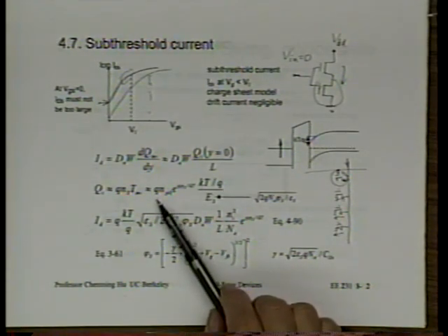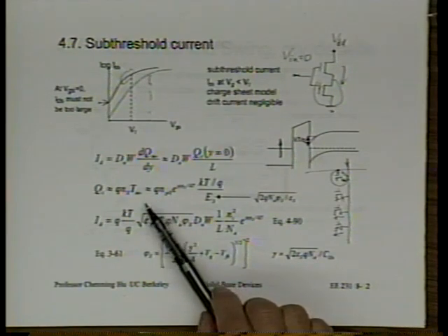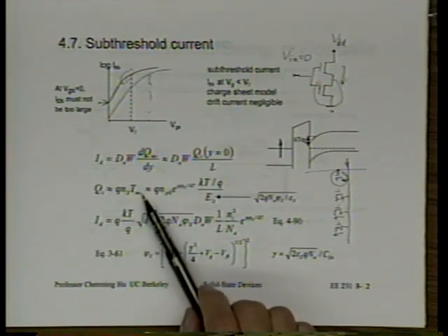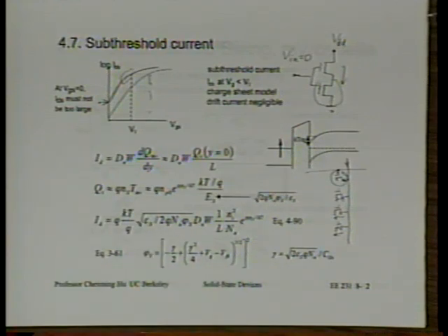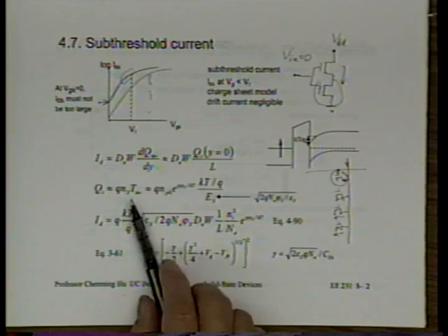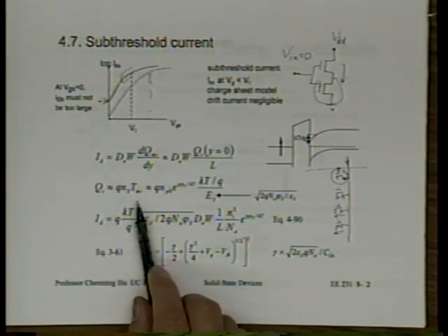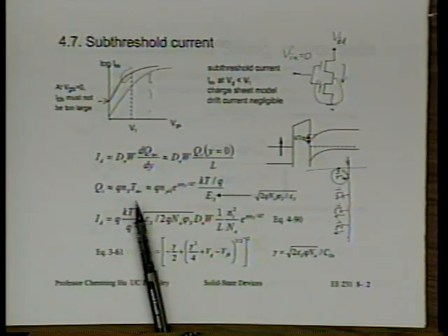So, by the way, if we use the quantum mechanical analysis, how thick is the inversion layer? This is perhaps a slightly irrelevant question. Just in general, if someone asks you how thick the inversion layer is, if you answer 20 angstroms, it's a good answer because that's the typical inversion layer thickness if you solve the Schrödinger equation, right?